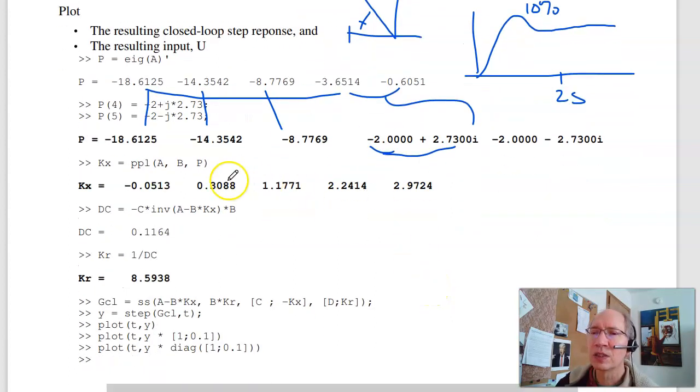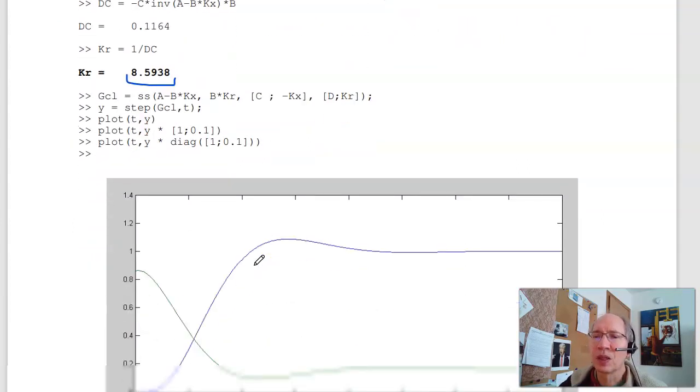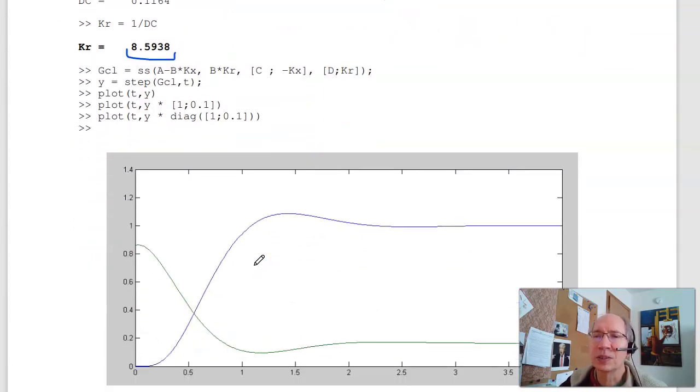So to do that, same procedure as before. Pole placement can do anything. Put the poles anywhere you want. If this is where I want to put the poles, here's my feedback gains. And it doesn't really care. Find Kr. Kr is bigger than before. It was 5, now it's 8. That's kind of telling me that it takes more control effort to get this response, which isn't surprising because I'm trying to make a heat equation oscillate.